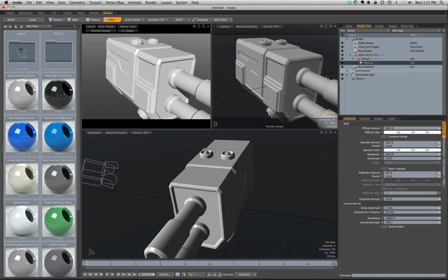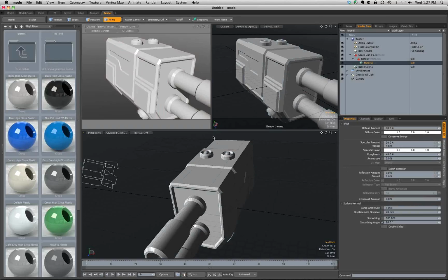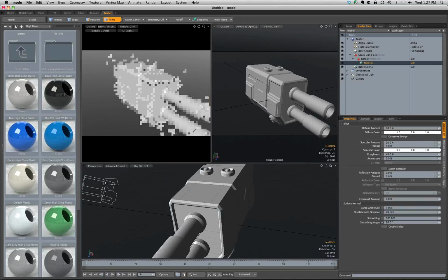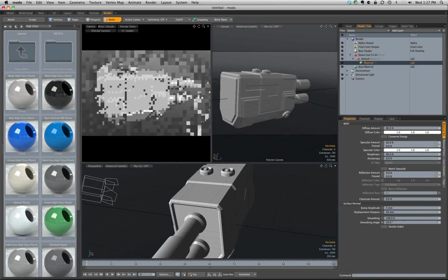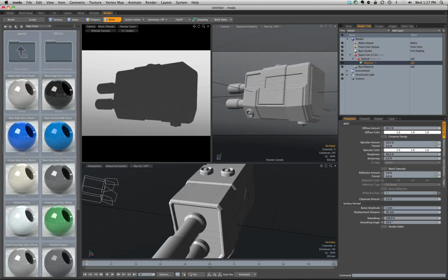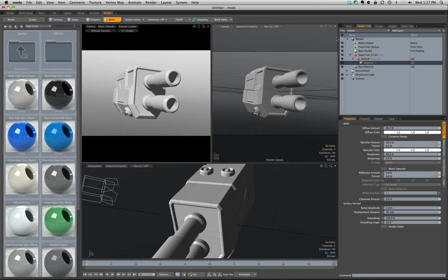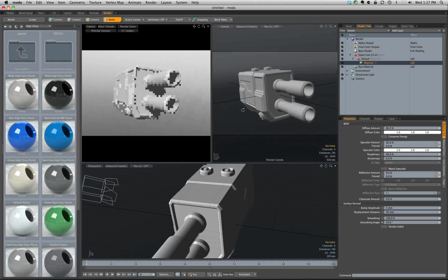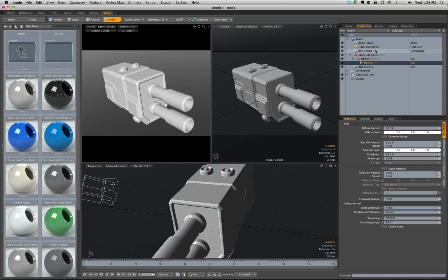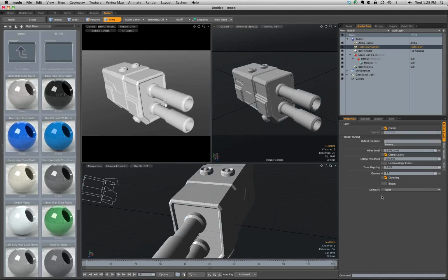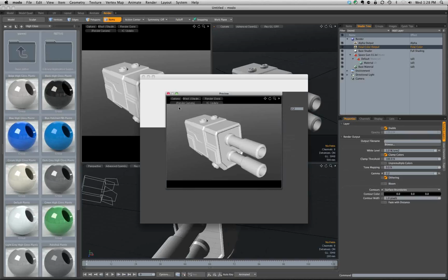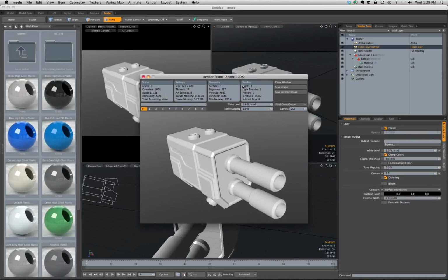But along these lines, as I was talking about rendering with edges, I know that's something people have wanted to do for a really long time. I've done a good bit of architectural animations, and that's always something the illustrators want. You know, I like really using the camera in 3D. As a photographer, I like really getting in there and moving things around like that. But often they want things very kind of just flat and not too much perspective, and often want to see the edges. So if you jump into the shader tree and go to the final color output, down at the bottom now in 501 you're going to find this thing called contours. And you could say surface boundaries, and what's going to happen, let me just press the F9 key, close that out. You can put the surface boundaries on.